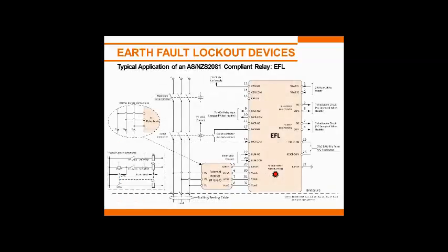So here's a typical connection to the relay. High voltage interface, a barrier. Now that can be external or internal, and the one shown in the picture was an internal one. This is also available in external, and that's obviously to go between the high voltage and then reduce the voltage to a much more manageable voltage, somewhere around a couple of volts, into the relay itself.